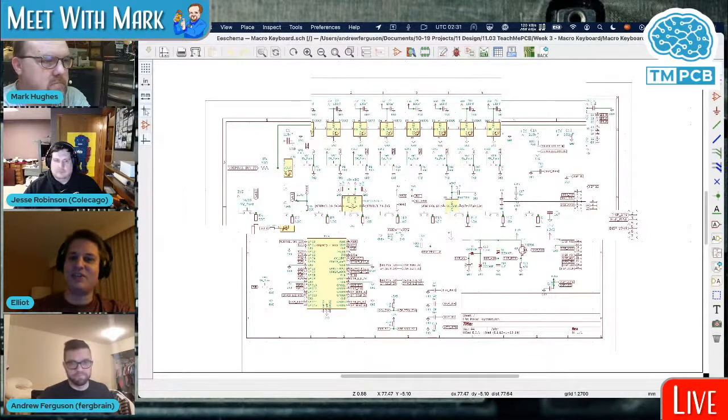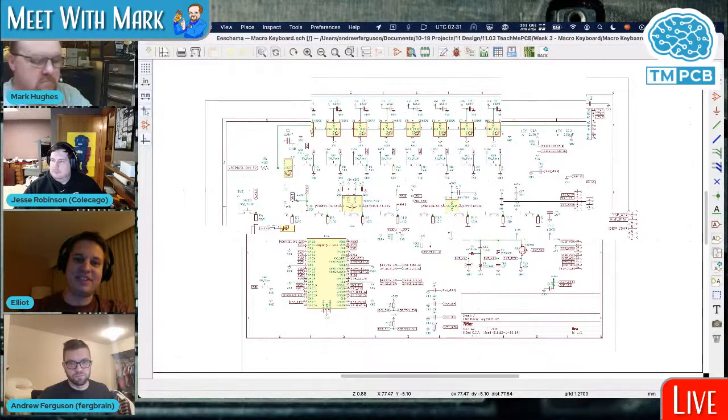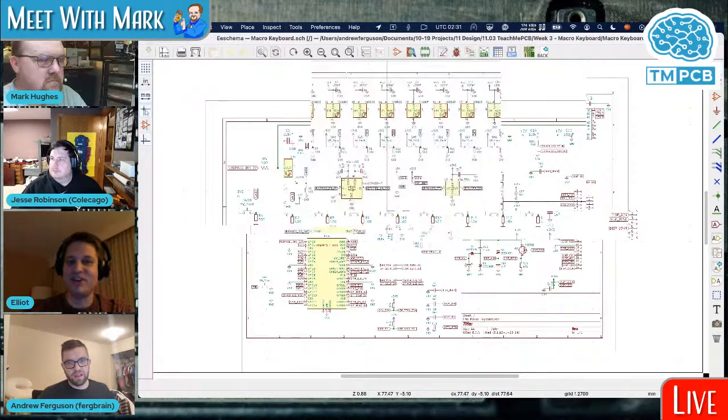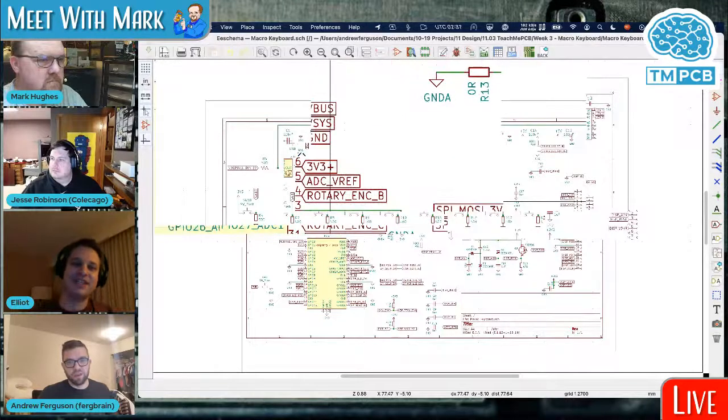And in the case where you're not having a lot of repetition, it probably doesn't make a big difference. But when you have that switch and the resistors like 8 times, that's where it really shines. Yep. Or 20 times or whatever. Yeah. And in this case, global labels aren't necessary, right? A net label is arguably harder to follow because they're on top of the lines. But when you have a lot of wires next to each other, it's hard to figure out which one goes to which. That would work in this case too.